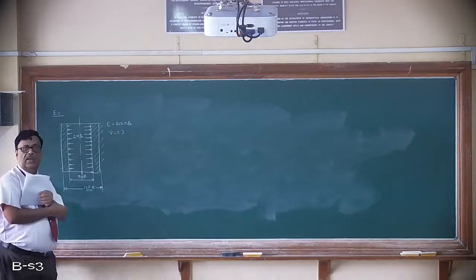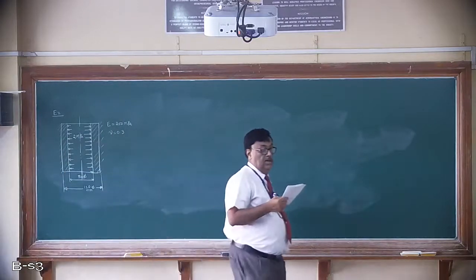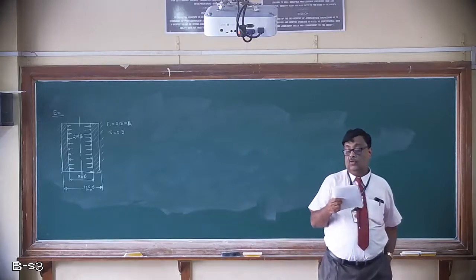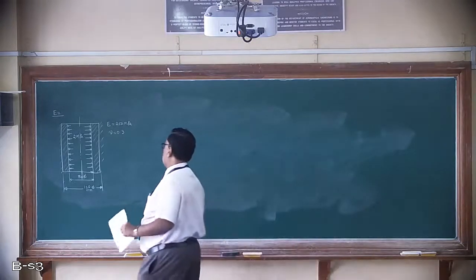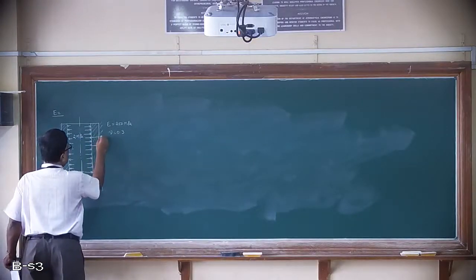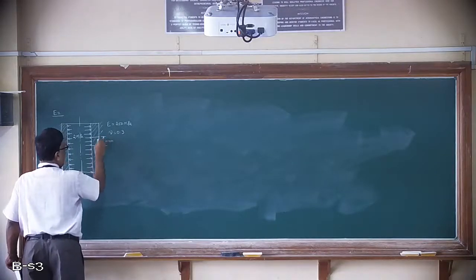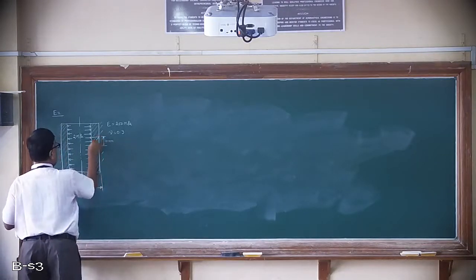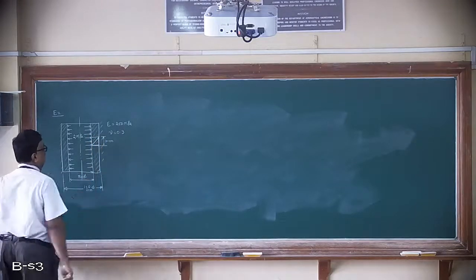Okay. So we are required to make a finite element model. It is definitely mentioned to use two elements on the 10 mm length. You have to use two elements here. If you consider the thickness, this is going to be 10 mm thick, and you will have to take two elements here, like this one element and this one element. See, what is the interesting point?